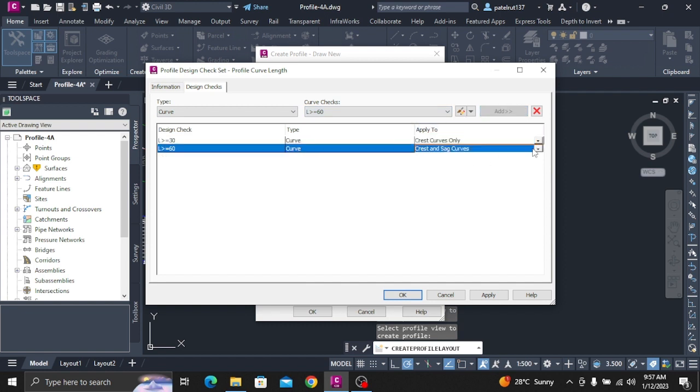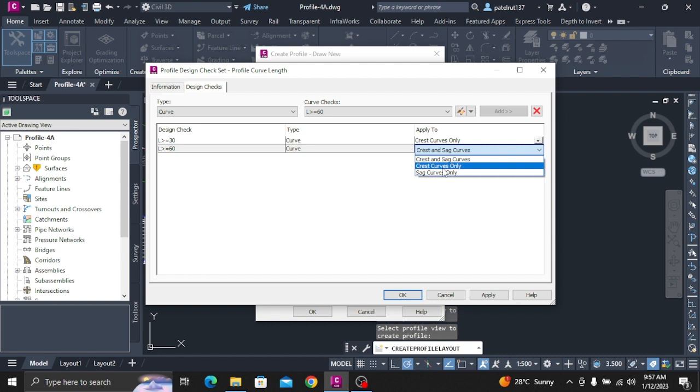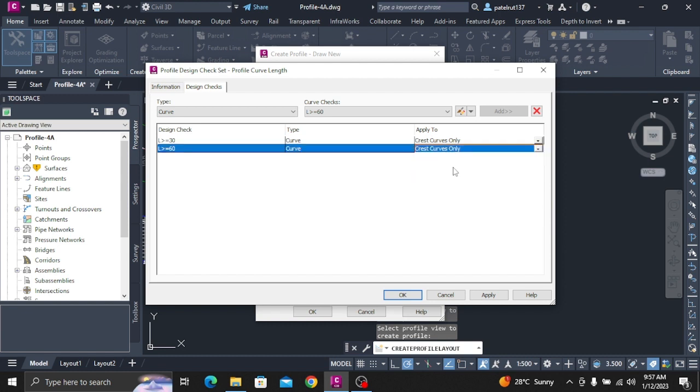15.000 foot. Click Apply. In the Profile View Properties dialog box, in the Split Profile View Data table, in the number 1 row, in the Profile View Style column, click. In the Pick Profile View Style dialog box, select Left and Bottom Axis. Click OK. Repeat steps 5 and 6 to change the profile view style in row number 4 to Full Grid. Click OK. Open Profile 5e.dwg, which is located in the Tutorials Drawings folder.